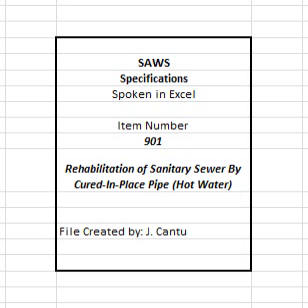The ends of the insertion excavation pit shall be sloped 2:1 or flatter, or proper shoring devices shall be used. Pits shall be placed and located to minimize the total number of pulls and maximize the length of CIPP, within the constraints of maintaining service and access and other requirements. When excess groundwater is encountered, it shall be removed by the contractor, and will be considered incidental to the project.